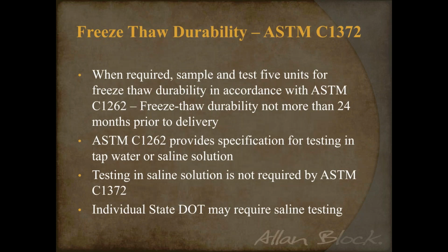So let's switch gears and talk a little bit about freeze-thaw durability. ASTM C1372 has it in as a requirement, but it's very particular. It says when required, sample and test 5 units for freeze-thaw durability in accordance with ASTM C1262. That's the freeze-thaw durability testing standard.